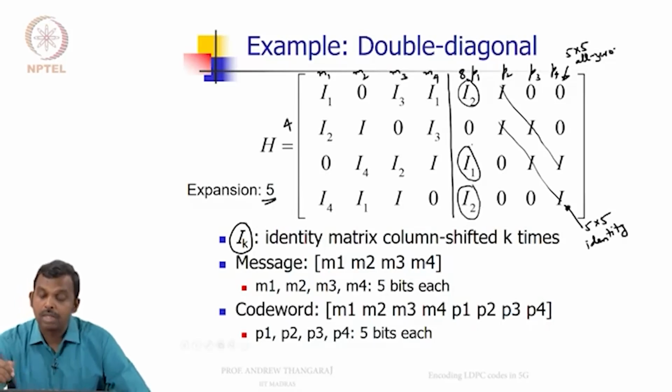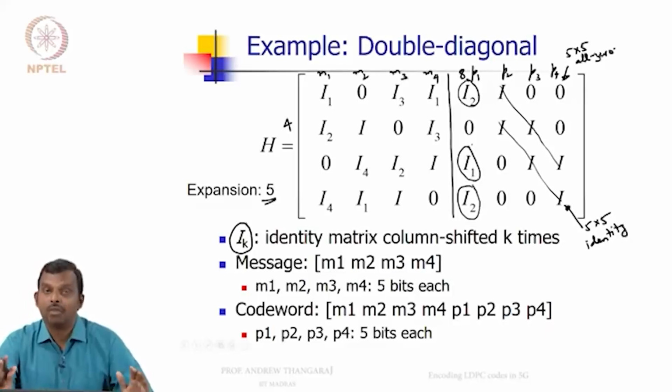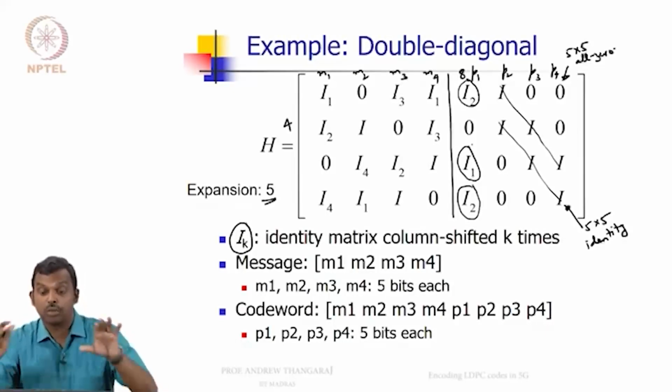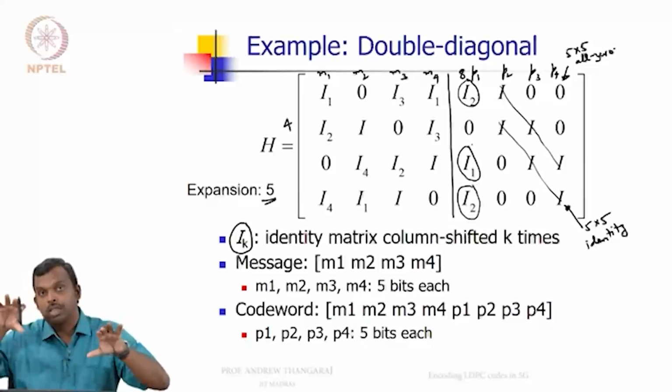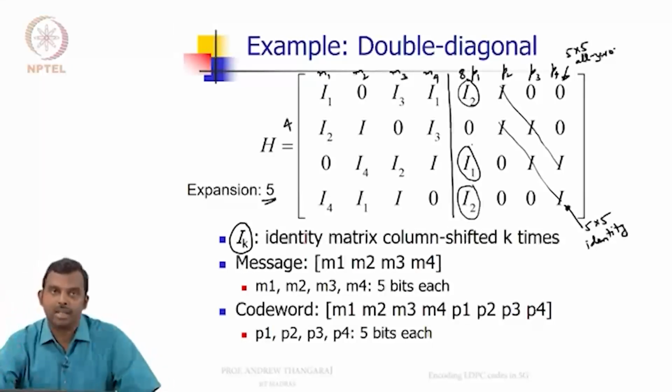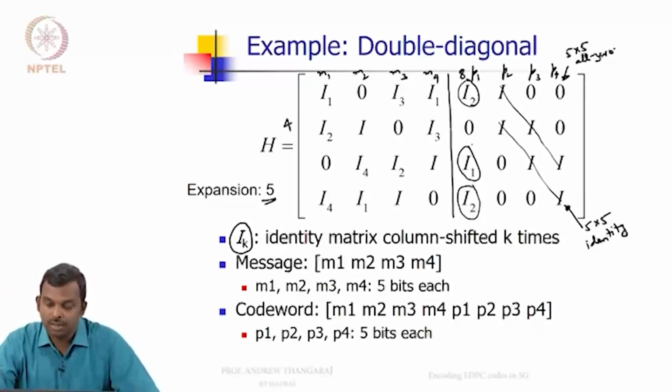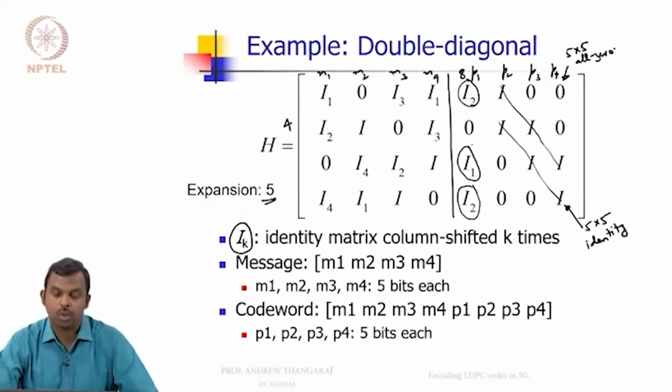This is similar to every base matrix in the 5G standard as well. If you look at the first 4 rows, the first 4 parity blocks, they will always have this structure. The structure is pretty interesting, and it's designed so that encoding can be easy. That's what I'm going to show you next.